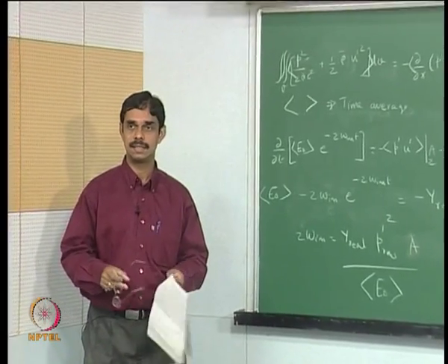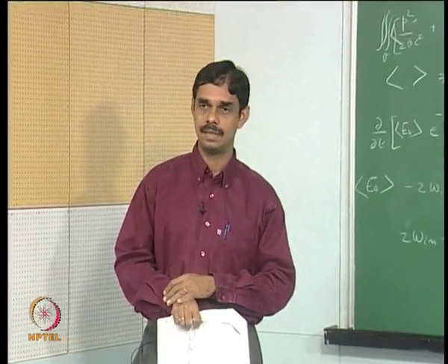With this exercise I try to tell you the reason why we are interested in measuring admittance of flames and so on, because the direction of energy flow would be determined by the sign of the real part of admittance, and it also translates to growth rate or decay rate. Any questions?